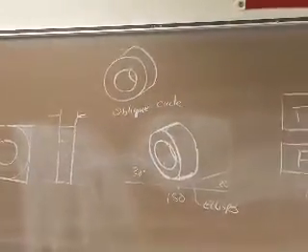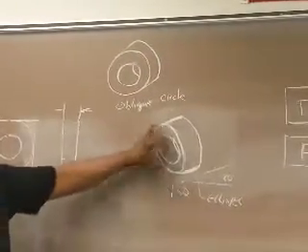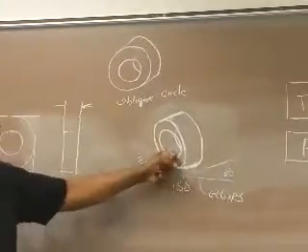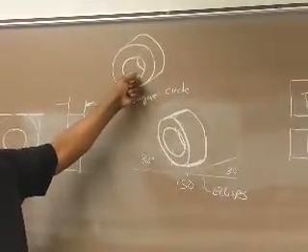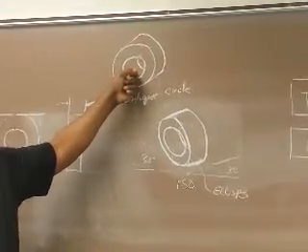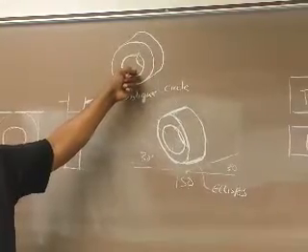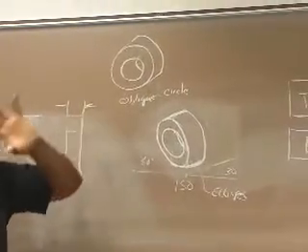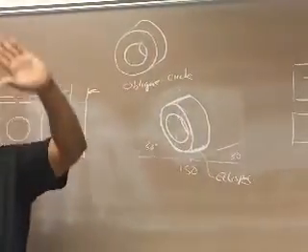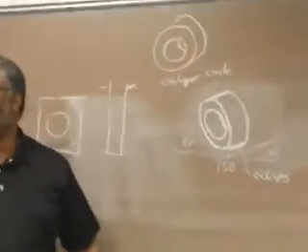So as far as what I'm presenting here, I'm presenting something that's easy to visualize, whether I look at it this way or look at it this way. But this is easier to draw because I'm dealing with circles. Here I have to deal with ellipses. So that's one of the things about obliques. When you have something and you can set it up where you get all circles that you're dealing with in the orthographic view of the oblique, then it's easier to draw.